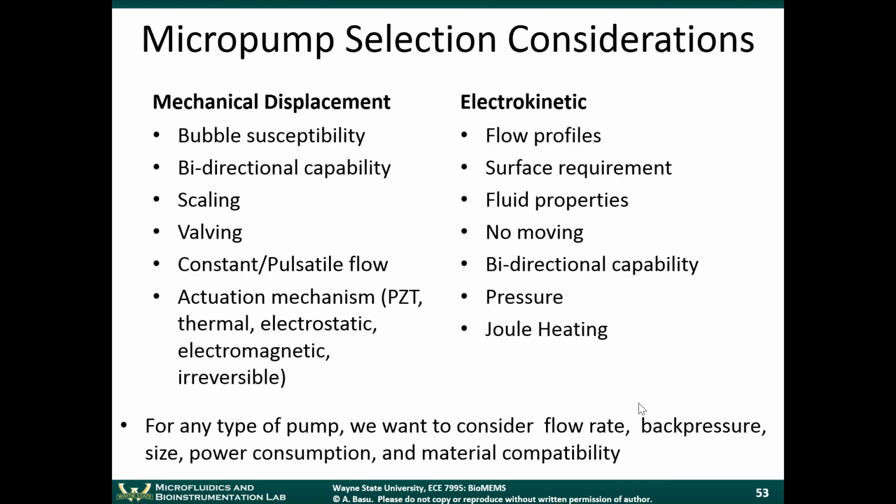So just to wrap up this module, the types of pumps that we talked about: one is based on mechanical displacement, mechanical movement, and the other, the dynamic micropumps, are based on adding energy into the system. In terms of microscale devices, both are used. In fact, I would say the mechanical displacement pumps are used more frequently than the electrokinetic and the other dynamic sorts of pumps. This just should say dynamic micropumps rather than electrokinetic.